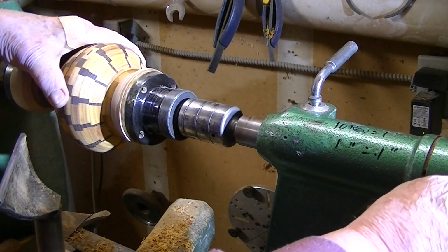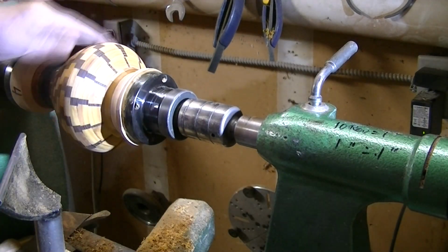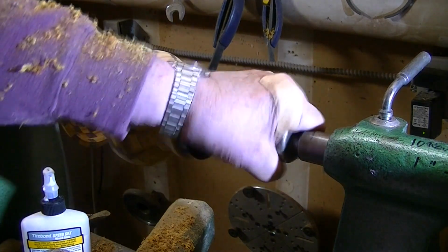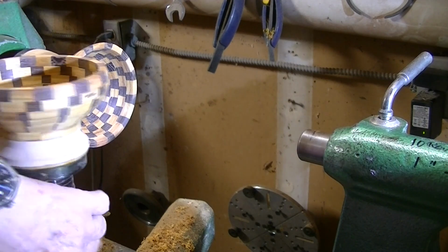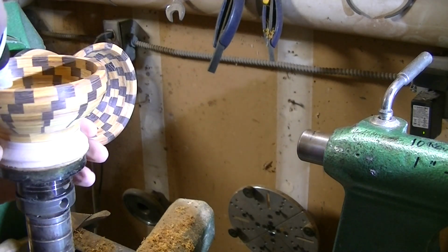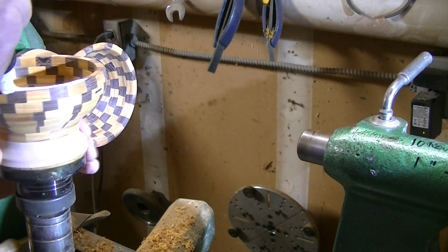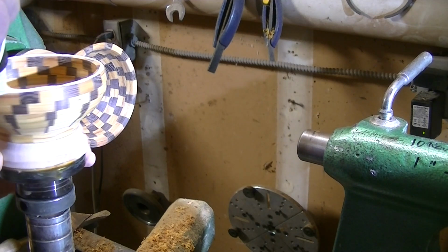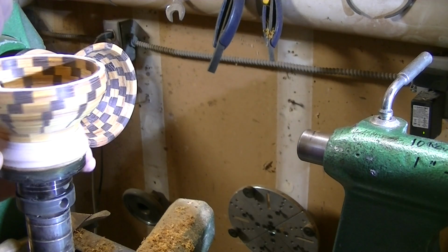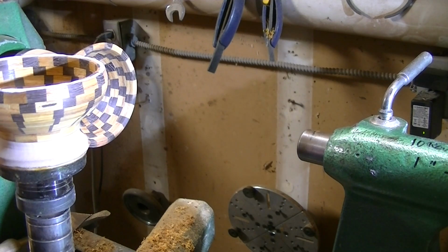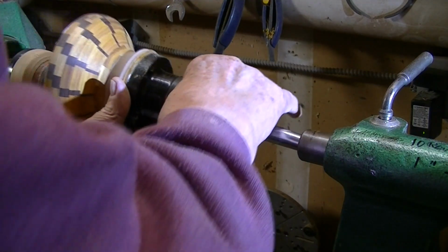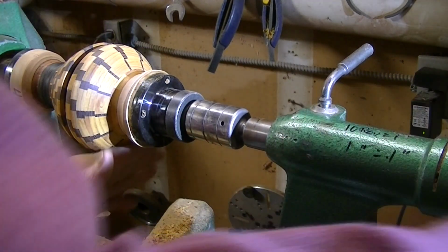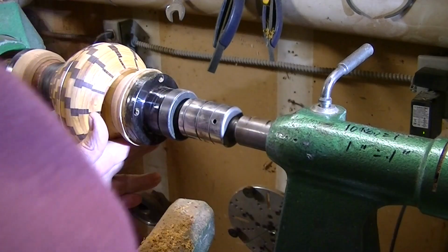And once I'm satisfied that I know where that joint is going to be, then I'm going to take the piece out of the tailstock, put it into where my tool rest post normally goes, and add a little bit of the glue and join the two halves together. Small bead of glue. If there's any seepage on the inside, that'll have to get cleaned up through the opening, a little scraping. If there's any on the outside, I will cut it away in the final cleanup. I will not try to wipe that glue away. The glue will get down into some pores and will cause the finish that goes on to be a little spotty in those points.